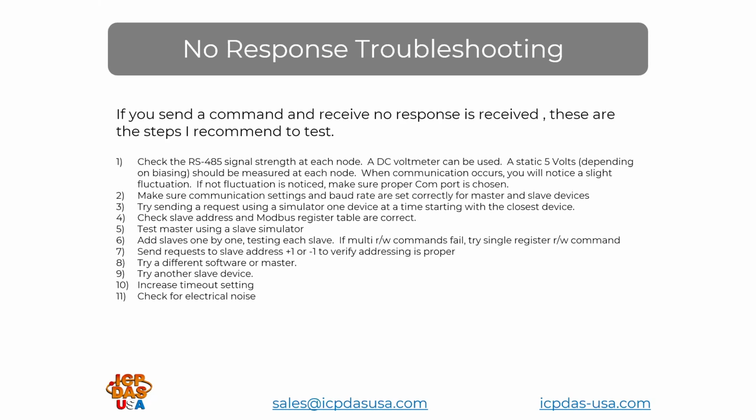Try connecting the master to a master simulator and test that you're reading and writing the correct register. Also, sometimes there are gaps in registers, so you are not able to read consecutive registers. That's why if you're troubleshooting one device and it's not responding, I would suggest just trying to read a single register value with a known value. That will help you verify you have the right register or the right sequence. Maybe you're reading one too early or one too late, but you'll have a good idea of that.